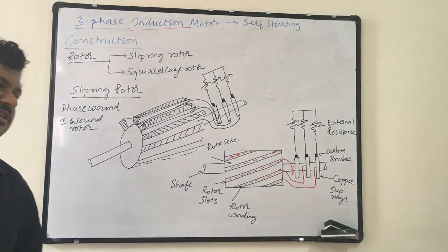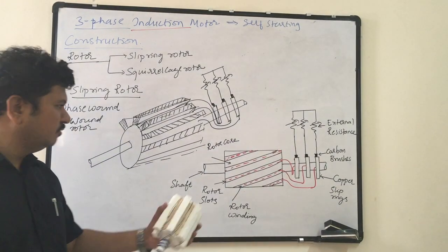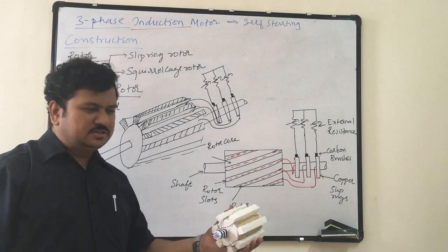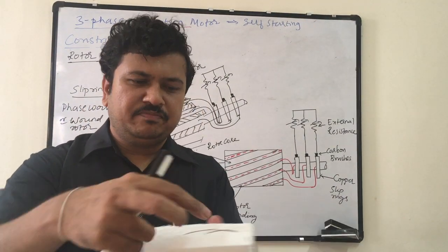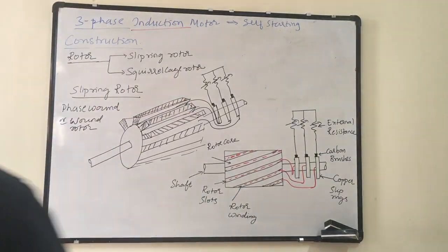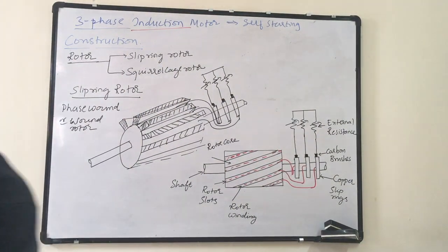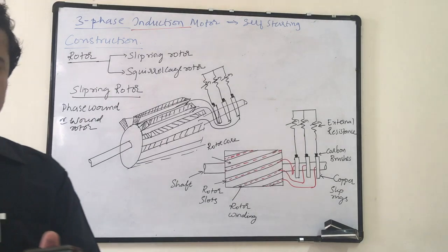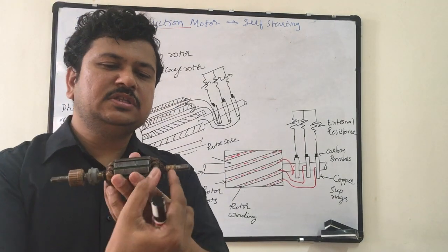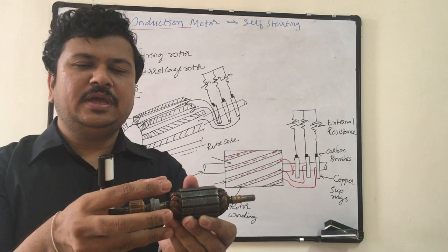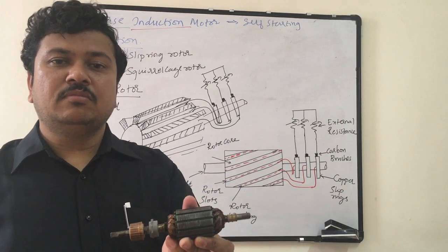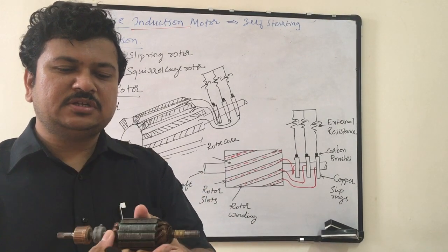This will add additional space in the motor. And because I am using winding, see here, this wire is coming out of the slot. This wire is coming out of the slot. So there is still a length of copper which is coming. See, this is the additional length of copper, this is additional length of copper. So I should make my motor lengthier. The cover should be covering this additional length also.